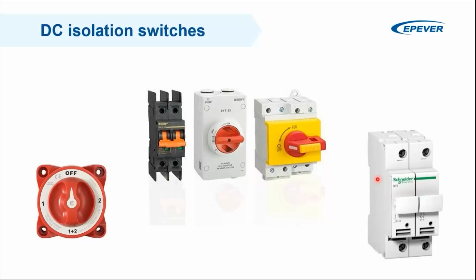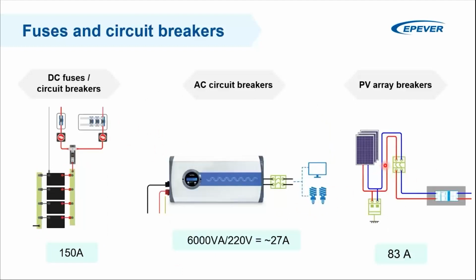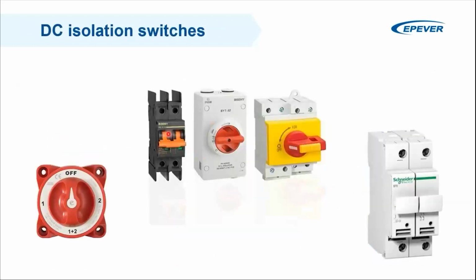Well, this is also an example of a rail-mounted or DIN-mounted circuit breaker for land-based systems, for battery PV systems. And normally, when the voltage is high, you use these sorts of fuse holders and breakers. And well, these are also the isolators for PV panels, for example. This also makes it easy. So we had a sort of, let's say, isolated here. You can use either these type of switches in your system just to make sure that you have safely disconnected the solar panel from your system.